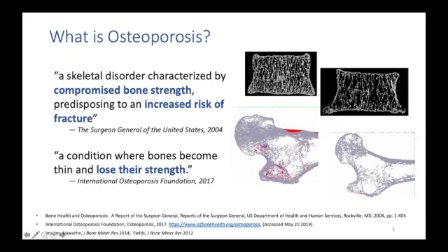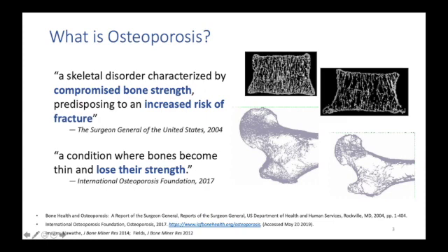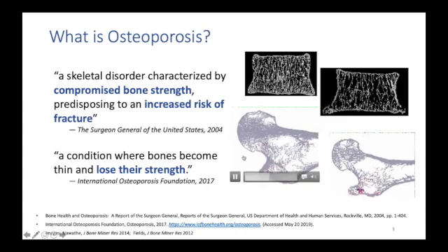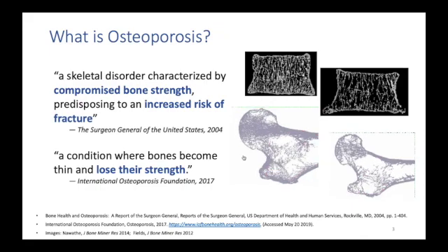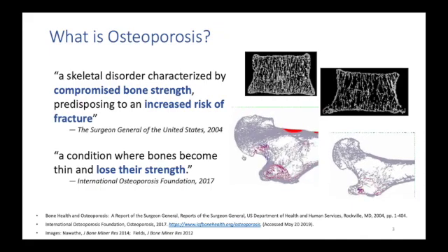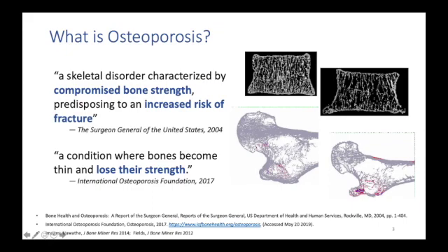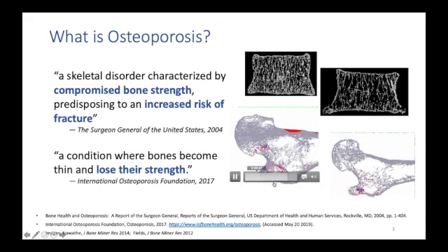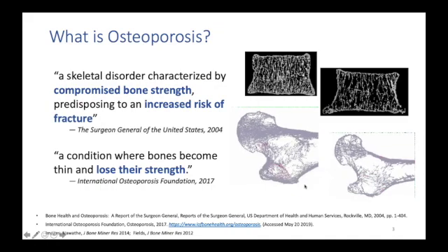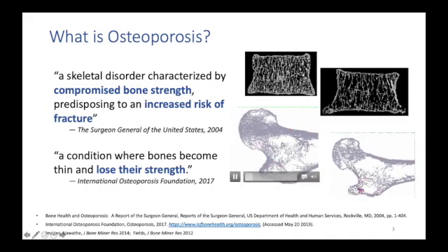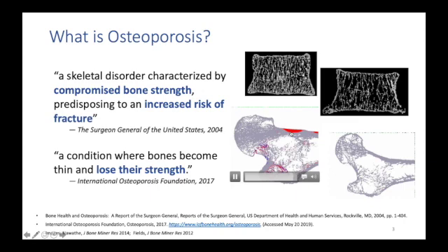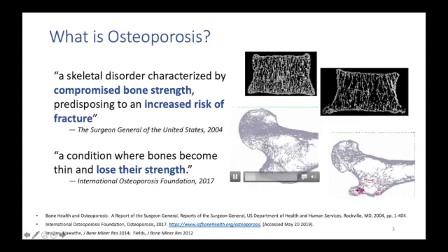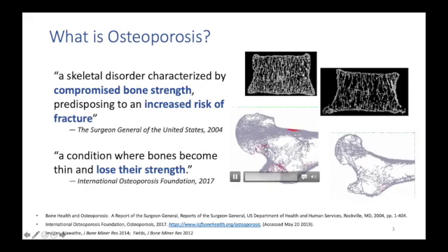And then on the bottom, you can see two femurs. These are computer models using finite element analysis to simulate a sideways fall. The femur is loaded at the femoral head, and it's supported on the greater trochanter on the bottom surface. And what you're looking at are regions of failure. Red means that the bone tissue has failed in tension, and blue means that the bone tissue has failed in compression.